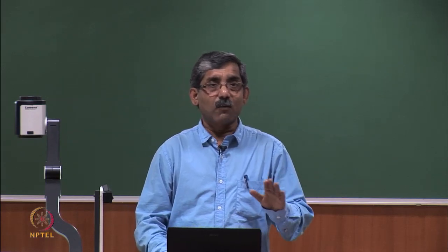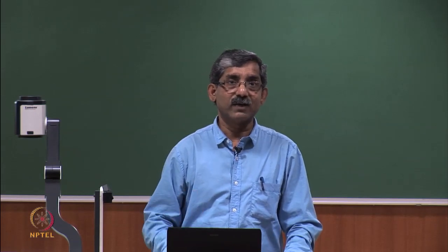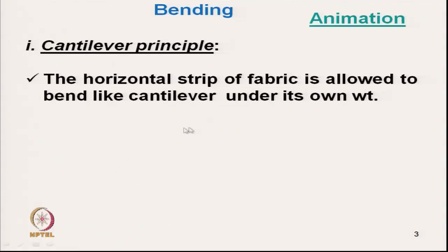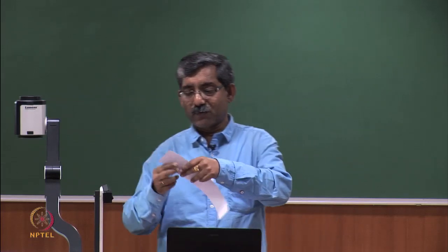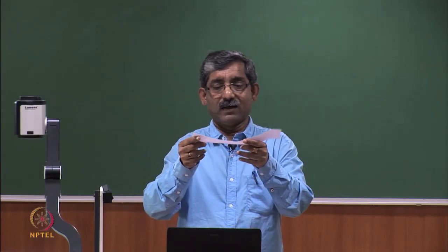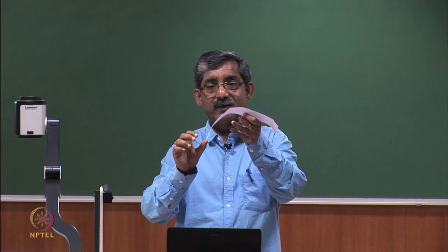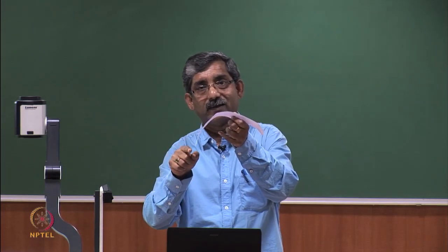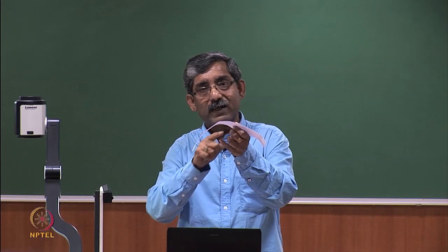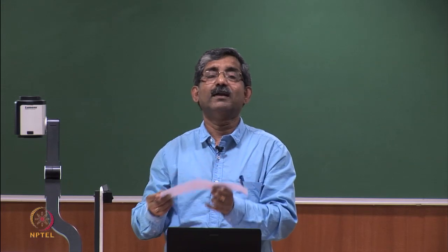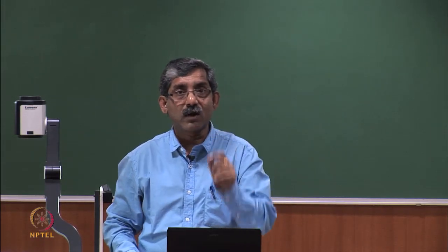The common method is the Shirley stiffness tester, where a horizontal strip of fabric is allowed to bend like a cantilever under its own weight. Suppose this is a fabric sample on a horizontal platform and we let it hang under its own weight, this fabric will bend. From this bending angle or from the overhanging length we can calculate the flexural rigidity of the fabric.